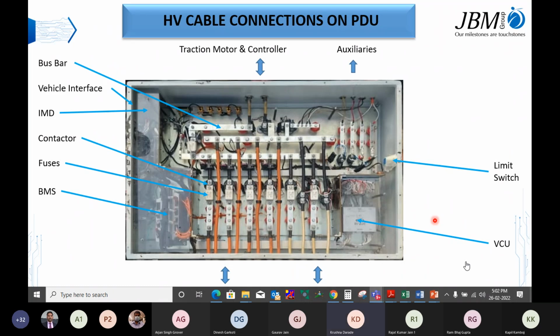Hello Kapil, I have one query, sir. Yes, ask, continue. Actually, we are using two BMU right now, one master and one slave. What is the difference between both, sir? The only difference is that one BMU can measure only 3 battery currents. We have used here 4 current sensors. Yes, sir. Okay, so yes, this master is capable only of reading the value of 3 sensors. That is the limitation only. Oh, okay, sir. So the other one is reading the one only, but it can measure another 3. Yes, right.